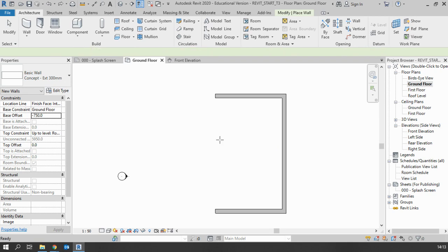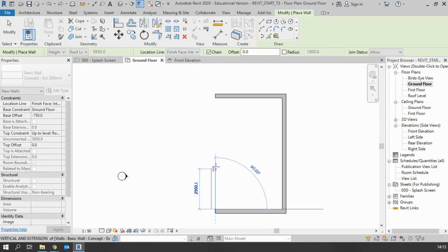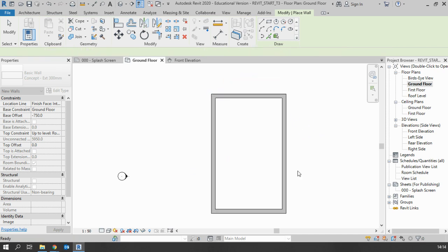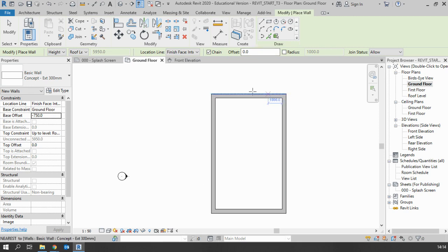So if I undo that, when you are modeling, make sure you follow straight lines. The guide should help you, and it automatically should snap to being in straight lines. But just be wary that if you're slightly off that line, it will model that wall at a slight angle. So the dash lines help you stay in straight lines. If I just model that there, and then click escape, that finishes the model off in terms of